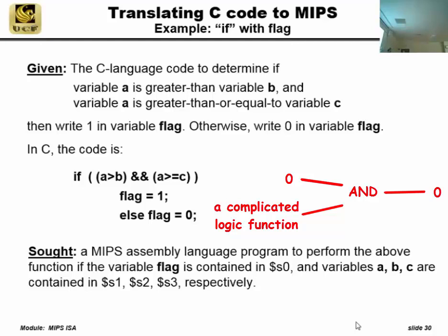This is a great final exam question, right? Because if you know what an AND gate is, you know you don't have to look at any of their inputs. F has got to be 0 because, and this is a little takeaway that you can write in your notes, AND is 0 sensitive. What does that mean? It's sensitive to the 0: any input of 0 makes the output 0. OR is 1 sensitive. Any time any input is a 1, the output's going to be 1 no matter what the other inputs are. So AND is 0 sensitive, OR is 1 sensitive.